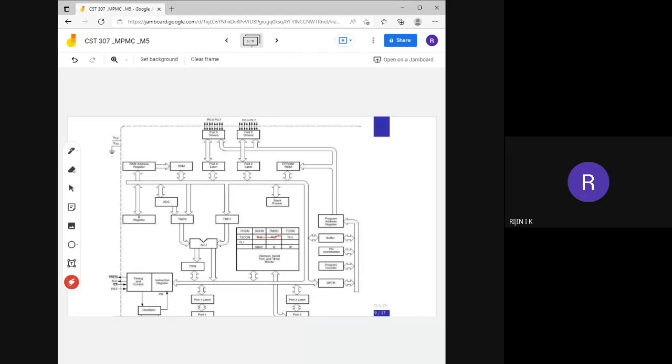Timer 0 will be represented as TH0 and TL0. That means timer 0 higher order and lower order bytes. Timer 0 is a 16-bit register. So TL0 represents the lower order byte of timer 0, and TH0 represents the higher order byte of timer 0.